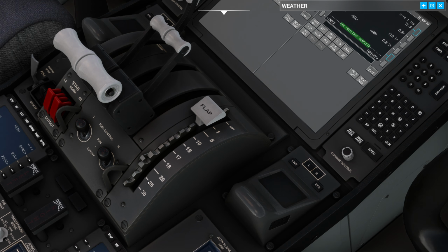We only take off up to flaps 20, but what it affects us is quite little, really. The airplane feels pretty similar. There's a slight difference in the weighting, but yeah, you have different flaps as needed. The point is, we'd like to use the least flaps possible, because if we're using a higher flap setting and you have an engine failure, you have more drag outside, and as a result, the engine has to be run at a higher power setting.